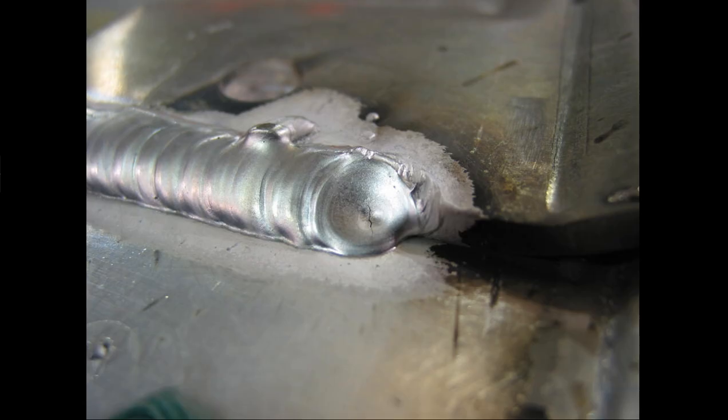The next one is an oversized weld. It's a bracket that went in place, and when the bracket closed, when the weld closed, the bracket and this big lump of material here pulled the heat out of it very quickly. And this was done by TIG, and the person did not add filler material and terminate with their finger control or their foot pedal at the correct rate.